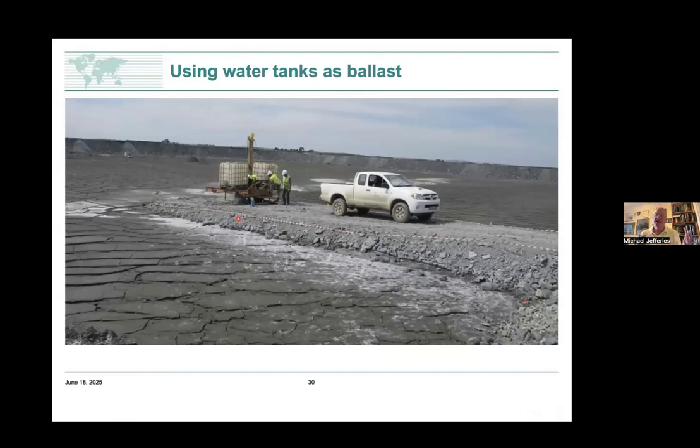And this is just an example that if you say, well, I've got to go cone testing, you don't necessarily have to use a big cone truck. There are other ways of getting reaction, and it's reaction that really controls what you do, because the electronics will remain the same. We're using the same recording systems into a laptop computer these days.